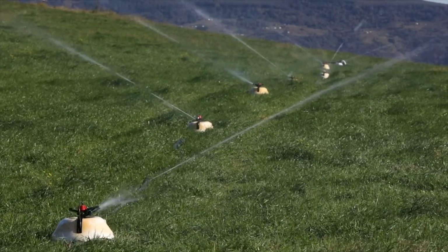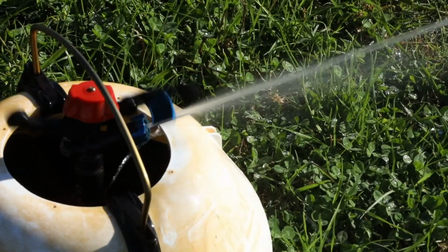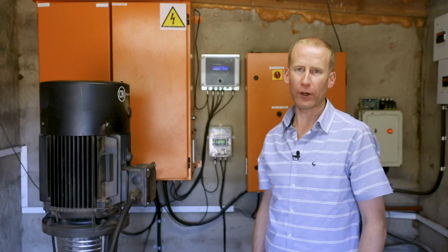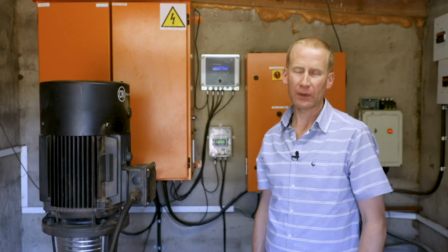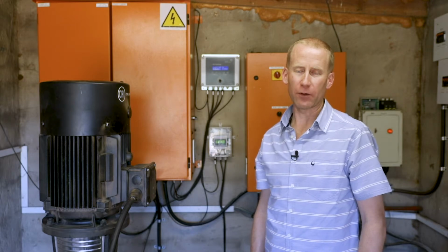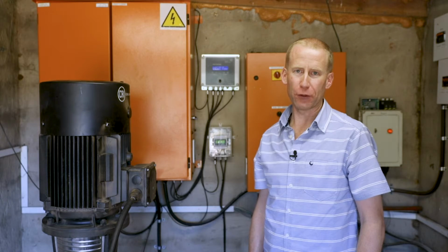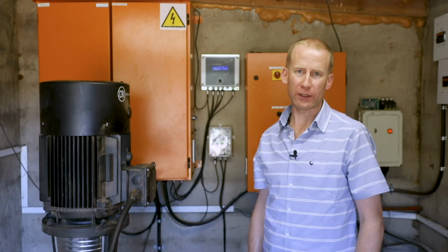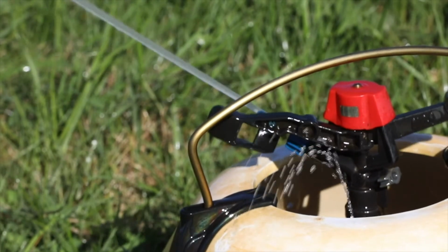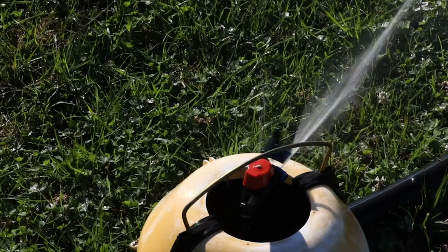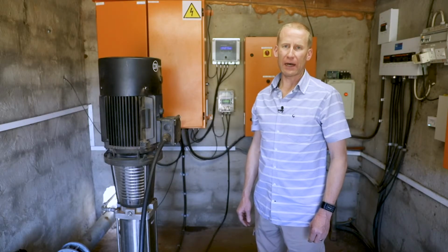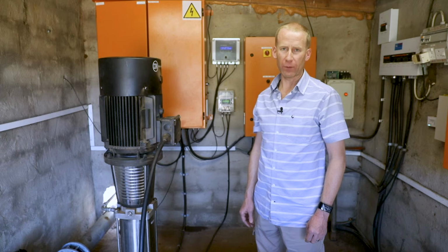The system will also control the pressure of permaset or pod irrigation systems. A single pressure monitoring station is installed at the furthest and highest point in the pod or permaset system. This allows a constant pressure to be maintained at the nozzles, even if they are very different block sizes. Different block sizes usually result in different flow rates, which result in different pump outlet pressures and different pipe friction. By controlling the pressure at the nozzles, we manage to ensure that there's a uniform flow rate throughout the pod or permaset system.